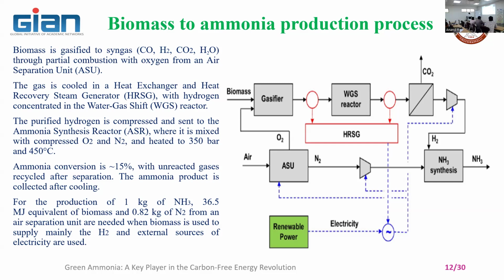So if you want to use it in an engine for producing power, you can go for downdraft. If you want to use a steam thermal power plant to produce the power, you can go for updraft, because gas at 500 to 600 degree temperature is leaving.